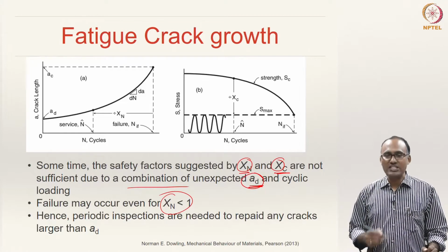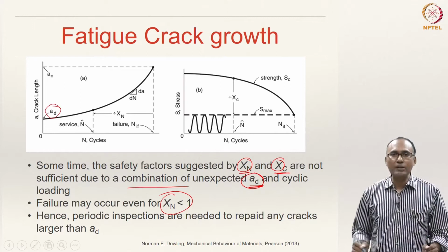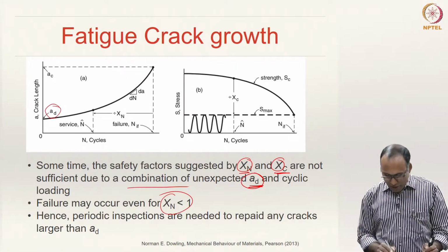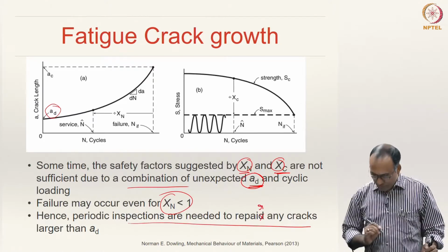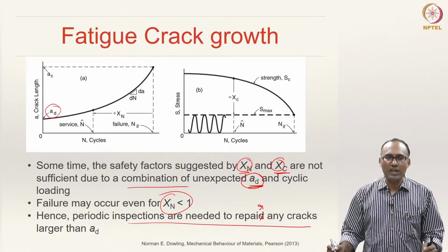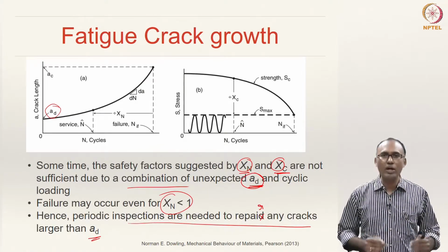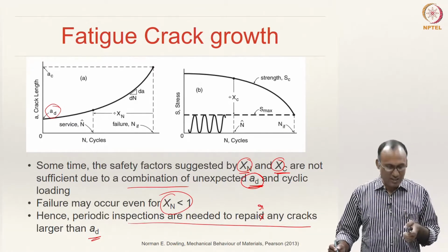Hence, it is extremely important to ensure that your detectable crack size is well within the safe limits, and hence periodic inspections are needed to repair any cracks that are larger than A_D. So, you are saying that my initial crack length, the detectable crack size, should not be greater than A_D. So, you need to ensure that they are indeed not greater than A_D.